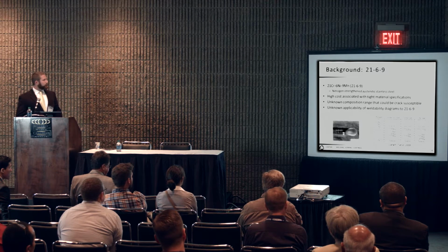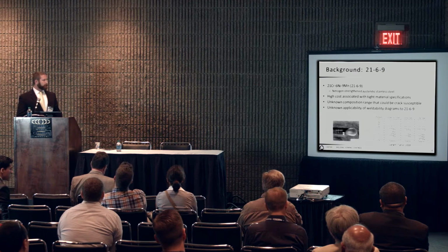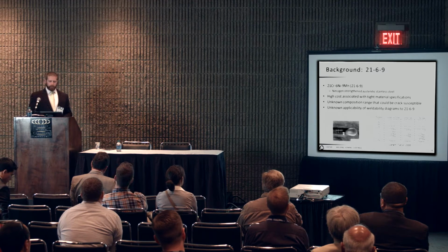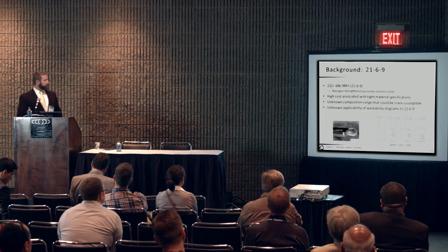And it's known that the weldability issue of hot cracking is there with primary austenite solidification. In the past, it's been dealt with material specifications with reduced sulfur and phosphorus contents. The high cost associated with these type of material specifications, as well as the fact that there's compositions within these ranges that could be crack susceptible, are both the motivation for this work. And then again, in general, there's an unknown applicability of the weldability diagrams generated for the 300 series stainless steels to these materials.